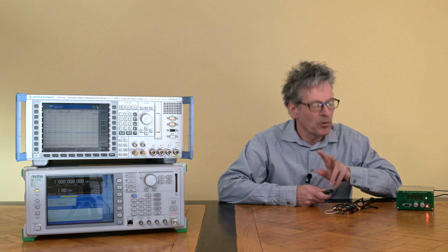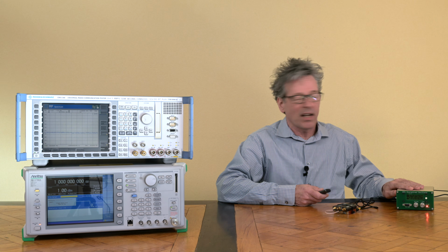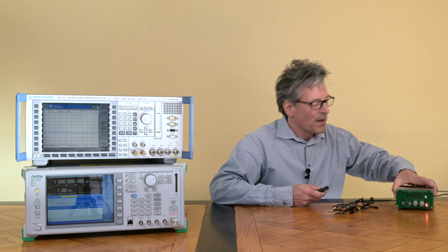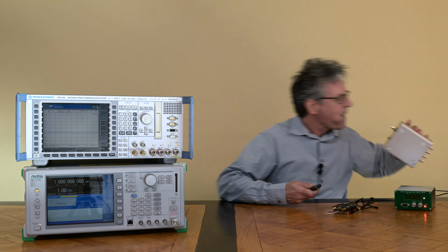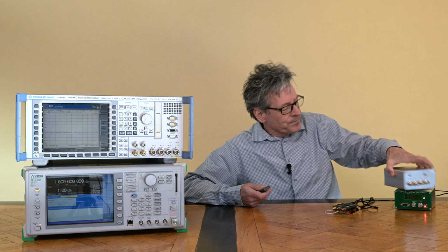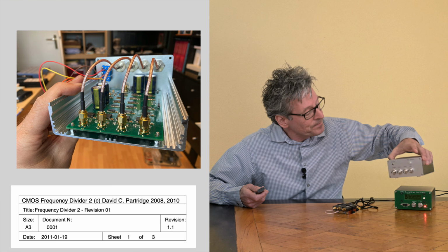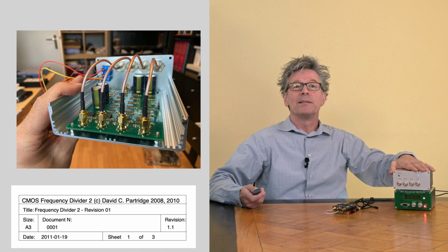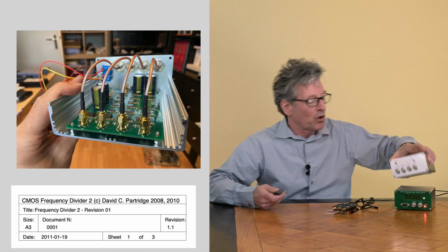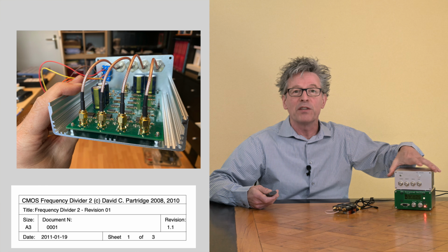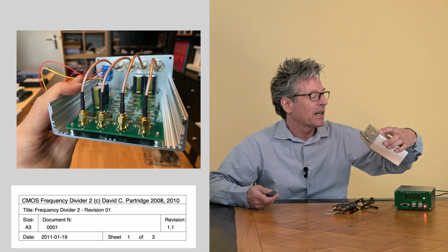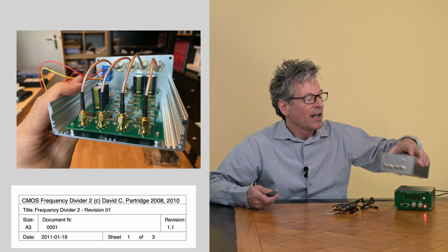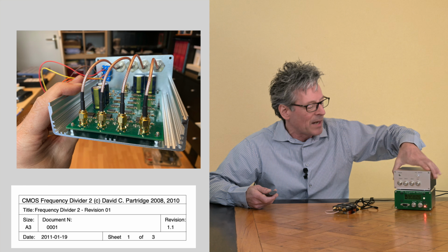Let me say a couple more things about this unit because it's kind of exciting. Maybe first of all, I built some additions to it. I built a nice frequency divider, because we only have one 10 megahertz clock here, and this way we have a couple of different frequencies coming out: 1 megahertz, 100 kilohertz, 5 megahertz, and also a selectable frequency.